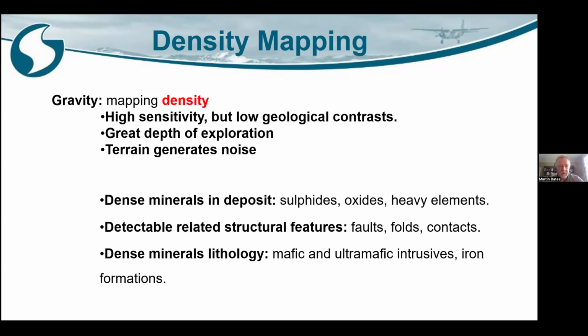Now, obviously, the majority of what you measure is the pull of the Earth. It's got a strong gravitational pull, and you've got a very, very small change in that, depending on how dense the rocks are that are closest to you or in the subsurface. Bigger bodies at depth will still create bigger responses, and smaller bodies near the surface can create a similar response, but over a smaller area. So you're looking down into the earth, and in theory, it goes on infinitely, but of course, the signal does drop off exponentially. So you're not going to see it forever.